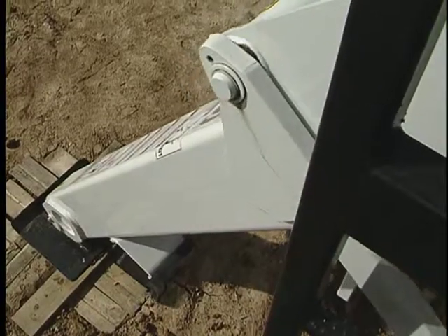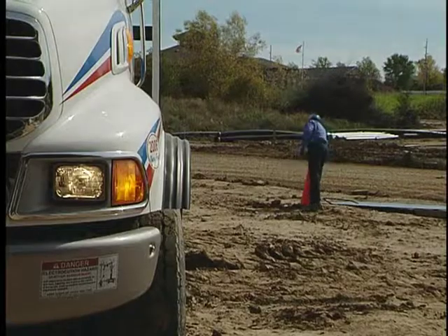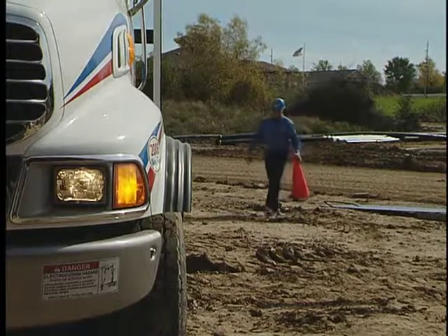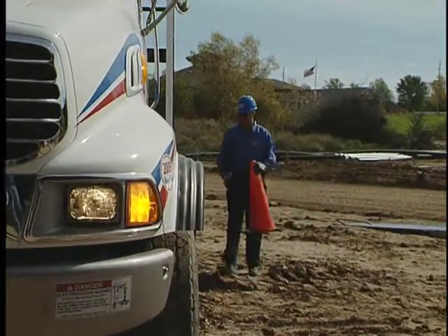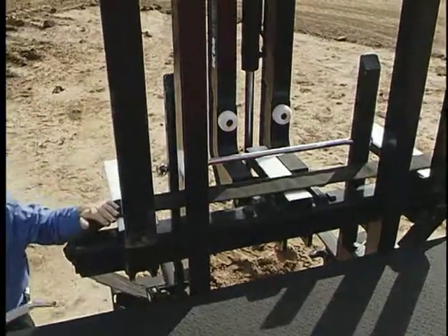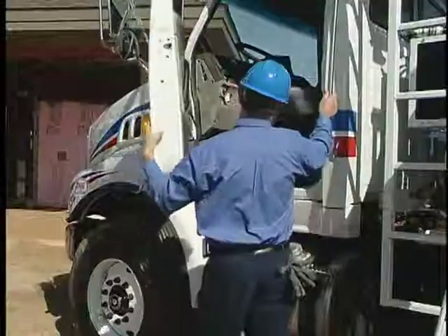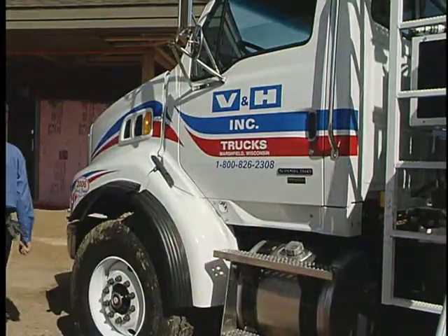Next, raise the outriggers and put them back into their original stowed positions. Be sure to pack safety zone equipment, cones, and caution tape. Clean up the area around you. And secure loose items on the truck. Check the grounds for any new obstacles that may have arrived on site before leaving.